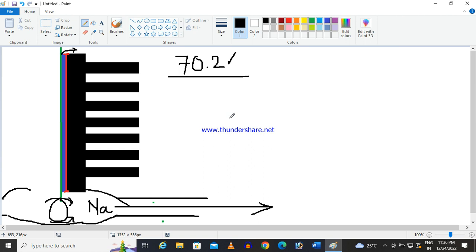But here, seat leakage is not that important or of interest, because it will be inside the line, not that much of a problem. But if there is a gland leakage, it will be very difficult. It is dangerous, because when liquid sodium comes out and contacts air, oxide formation occurs, which is an exothermic reaction, and there may also be activity in the secondary side.